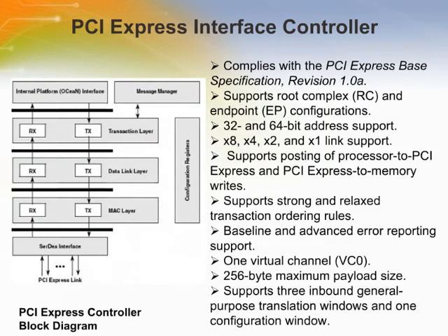The PCI Express controller provides the mechanism to communicate with PCI Express devices. The PCI Express controller connects the internal platform to a 2.5 GHz serial interface. MPC8548E offers up to x8 interface links.